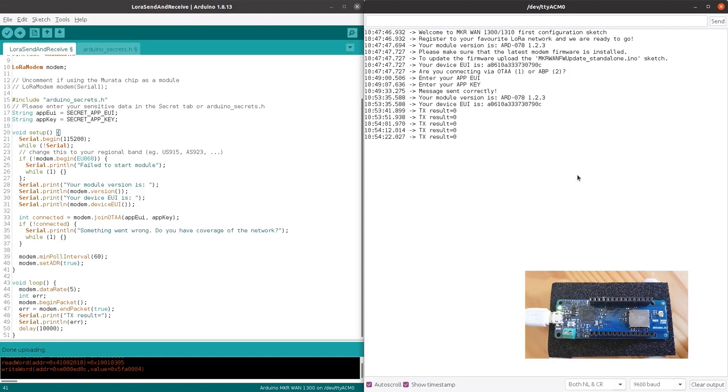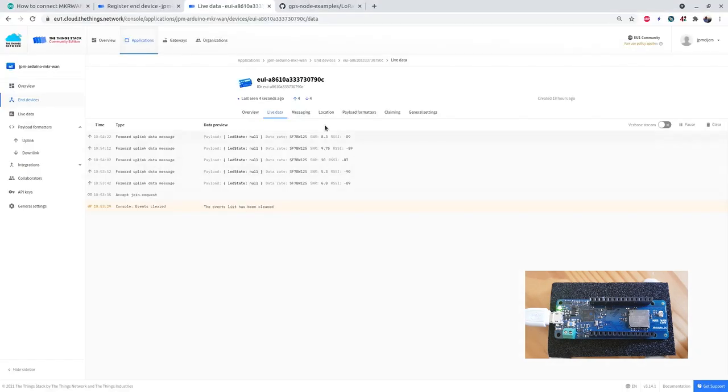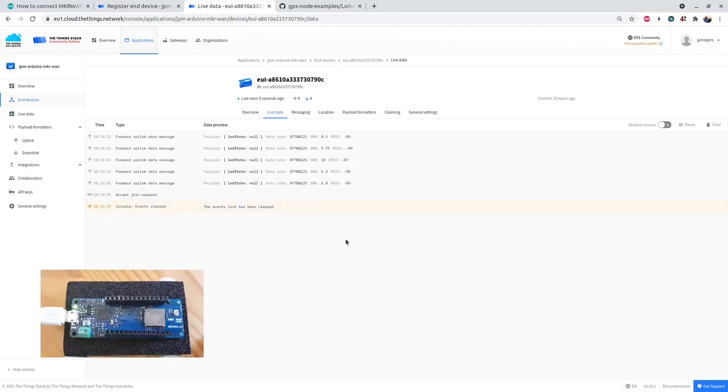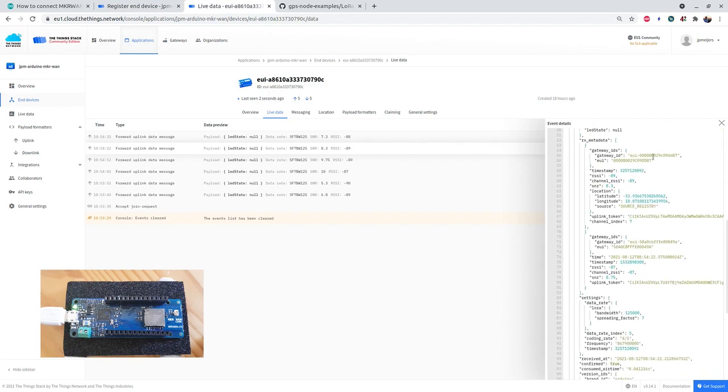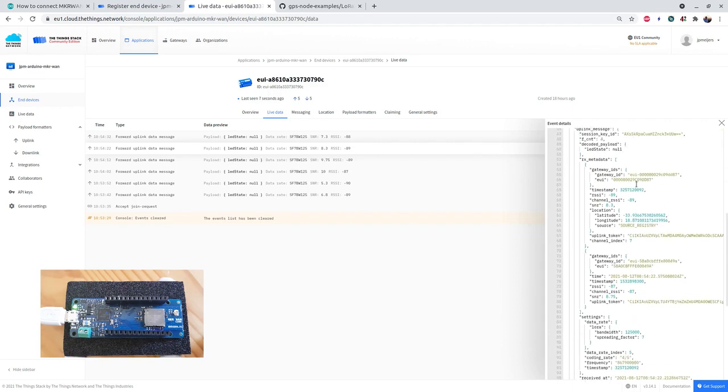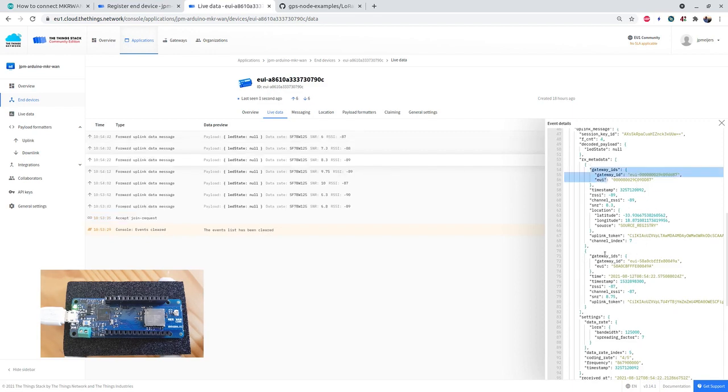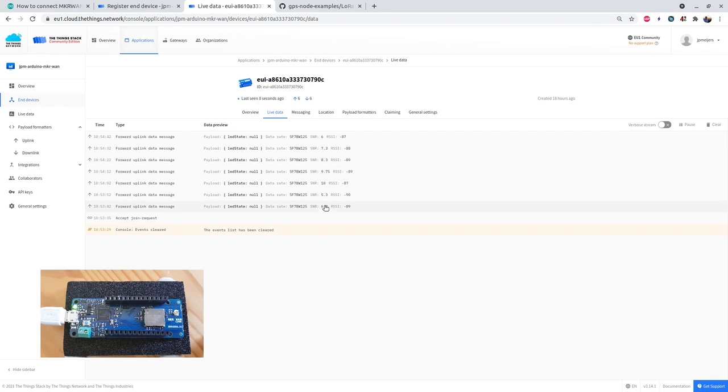So now what we can do is, on the console we have multiple messages, and we can keep an eye on the RSSI values here. Of course the order of the gateways we're not sure about, so in the case of multiple gateways like me, I need to open this again. And actually this is interesting, I only see 2 gateways here. 1 gateway, 2 gateways. The third gateway doesn't receive me this time. But we can easily now see the signal to noise ratio jumps around a bit. The RSSI value jumps around a bit.